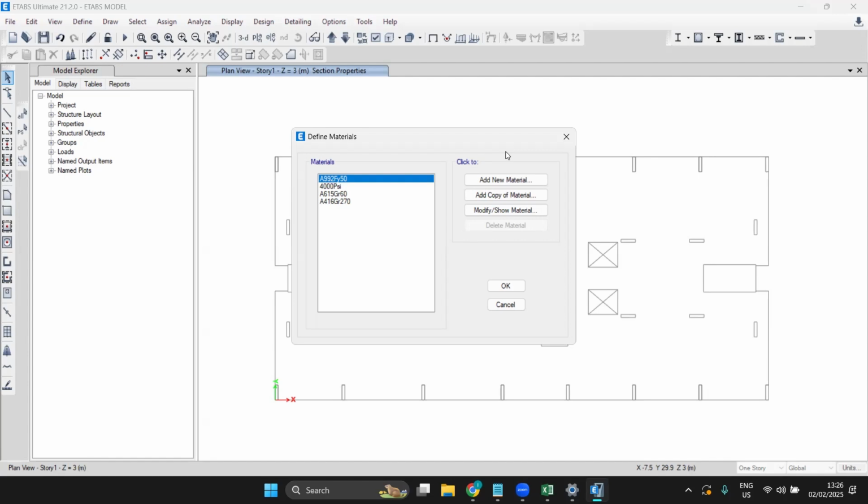I'm with you actually. I want only you to do the modeling. Create the materials of the concrete, create the reinforcement for the steel, then create the section sizes, and the walls you do have already. And create the slab thickness, assign the supports, assign the loads, and define the load cases and combinations. That's it. Actually, this is data entry. To be honest, the one which you did now is technical. The one which you are going to do now, anybody can do, because it is only data entry, right?